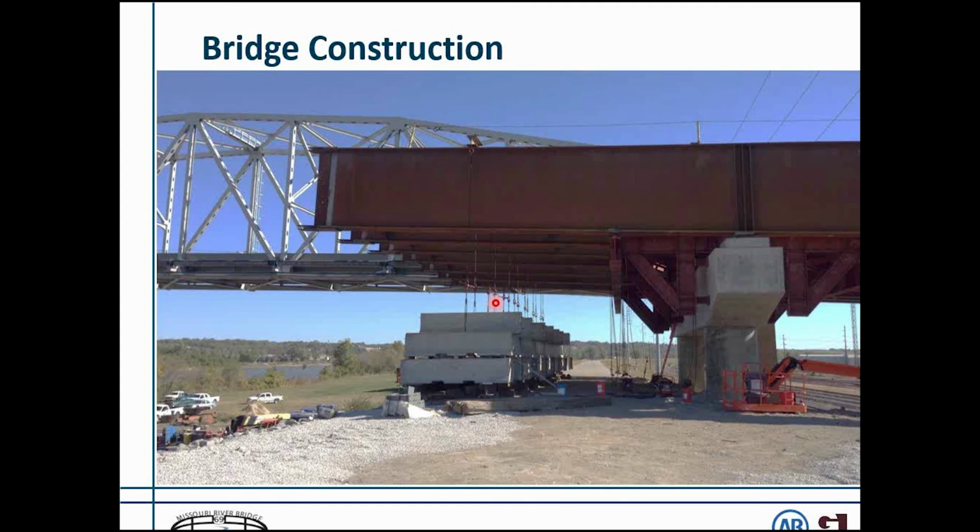So a little bit closer on vent 2, you can see how short that is and how important it is to model that in Midas to get the forces, because it is so short, which means it's very stiff compared to our taller piers, and therefore attracts a lot of force.